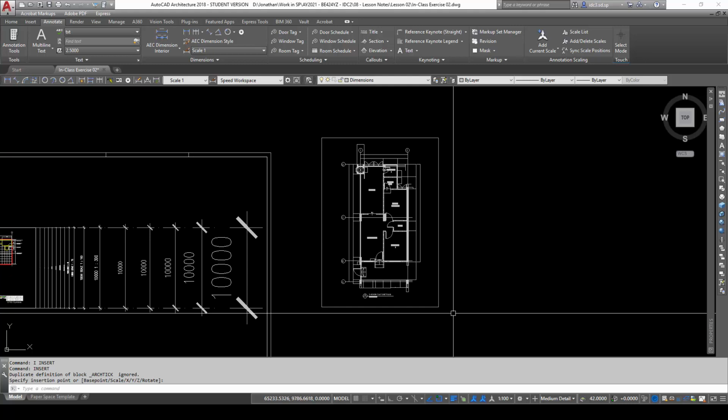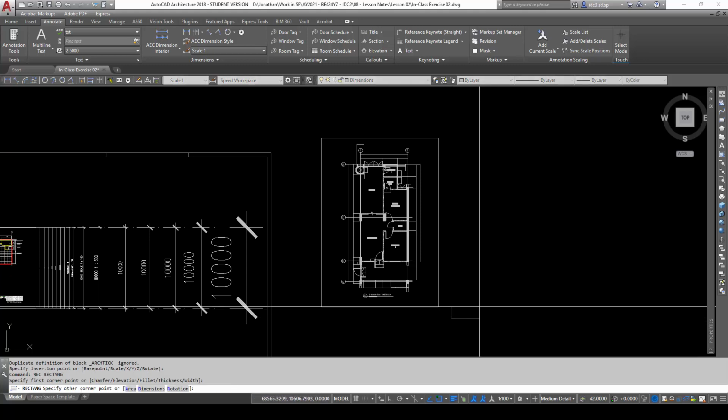So I'll just start with a guess with A3 size, which is the most common paper size that we use in the interior design industry, and also A3 size primarily because it is more printer friendly. Anything bigger than that makes it a drawing that requires a plotter to be able to print out the drawing properly. So it's considered the start of a large format paper size. So that's why we use A3.